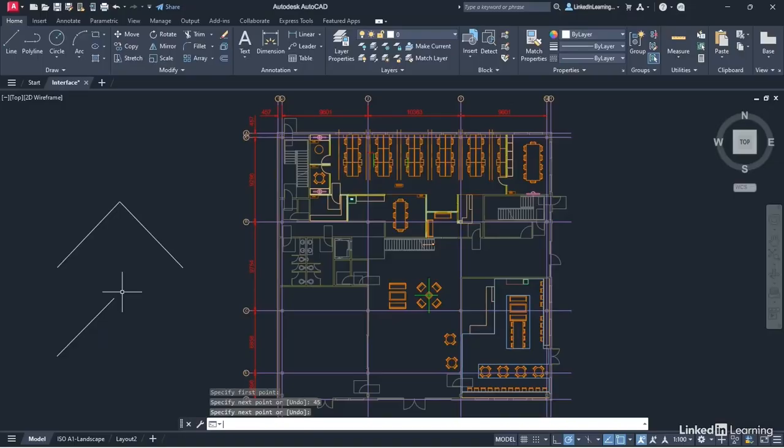And my suggestion is get used to it. It's one of the best ways of navigating input using the AutoCAD interface. It's great. And what I love about it is it always picks up when you start typing. So if I type polyline now, notice it's picked up the polyline command and also the polyline edit command there. Now that's on my suggestion menu.